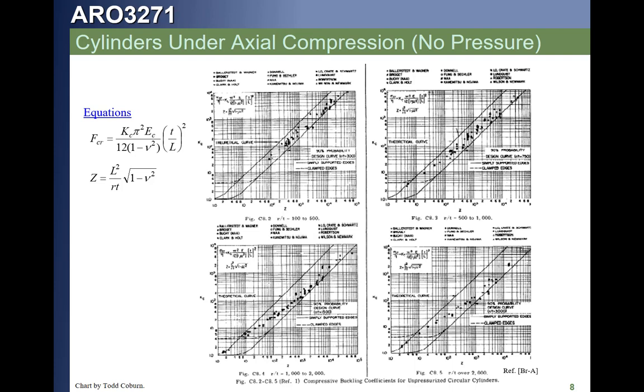We're going to ignore the theoretical curve, the upper curve shown for these, and just focus on what's called the design 90% probability design equation curve, which is the lower curve for all these four curves. You're going to need to take care to read this carefully so you get as accurate a value as you can. Our numbers within the class will tend to float a little bit based on how well you read that curve. I'm going to expect you to show a little bit of due diligence, but obviously, since you're going to be reading this curve, our numbers will differ a little bit and still be in the acceptable range.